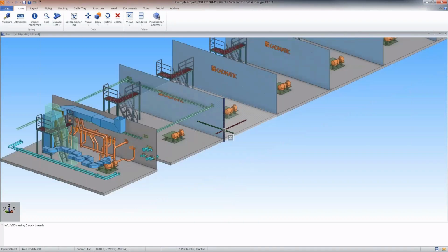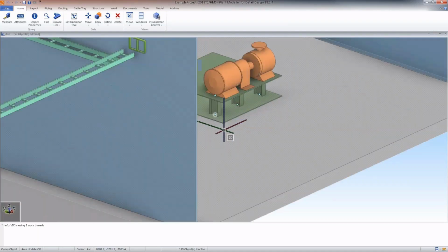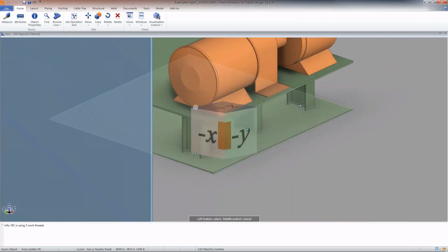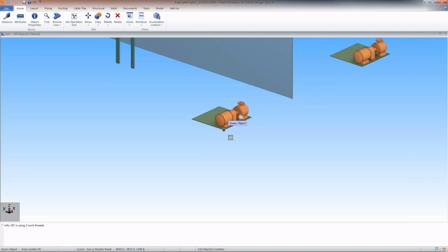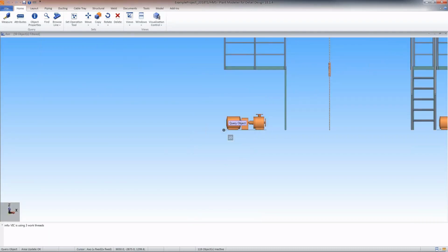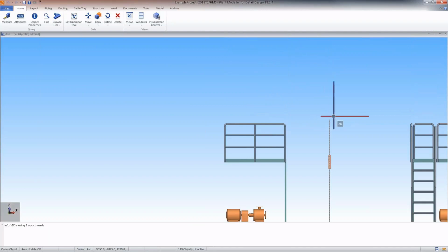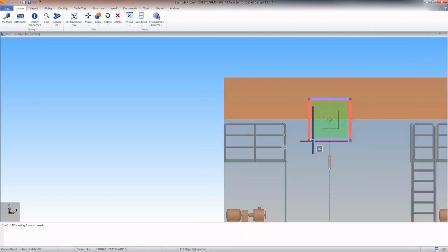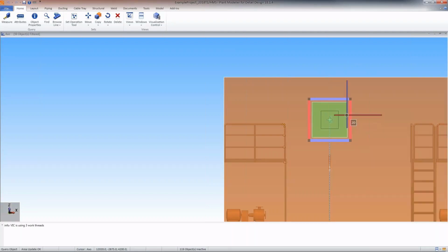So, for example, I can set all three axes minimum limits at once by hitting this corner, opening the cube with Control 5, and selecting the appropriate cube vertex. If our view is parallel to a main axis, instead of a cube, we'll see a two-dimensional selection box. But the functionality is essentially the same. We set our cursor's location, open up the filter box limit tool with Control 5, and select which side or corner we want to limit.